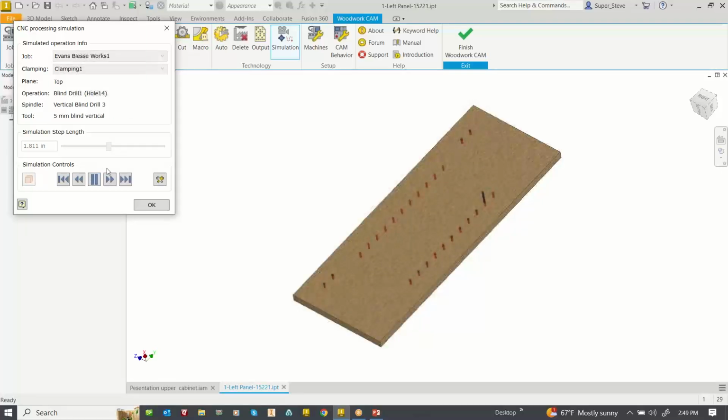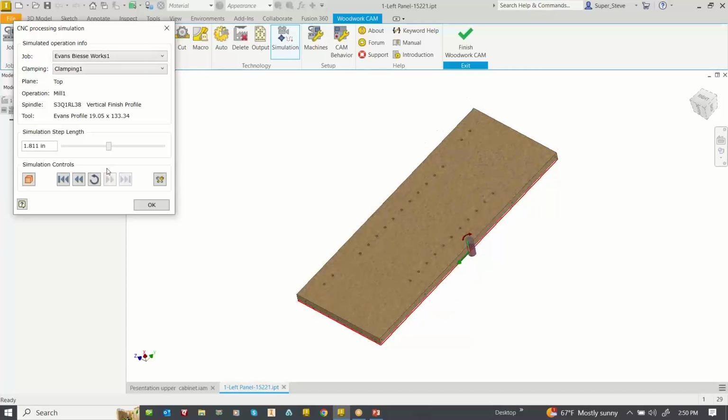So it's doing face boring. It's doing horizontal boring. Now it can't do it when nesting, but on single parts, I can now drill a horizontal or on angles, and it's all automatic. That's what's happening at this point. So doing rabbets, doing dados, doing pockets, doing milling, doing through drilling, doing sawing, because we can saw instead of mill if we want, and it's processing that data.